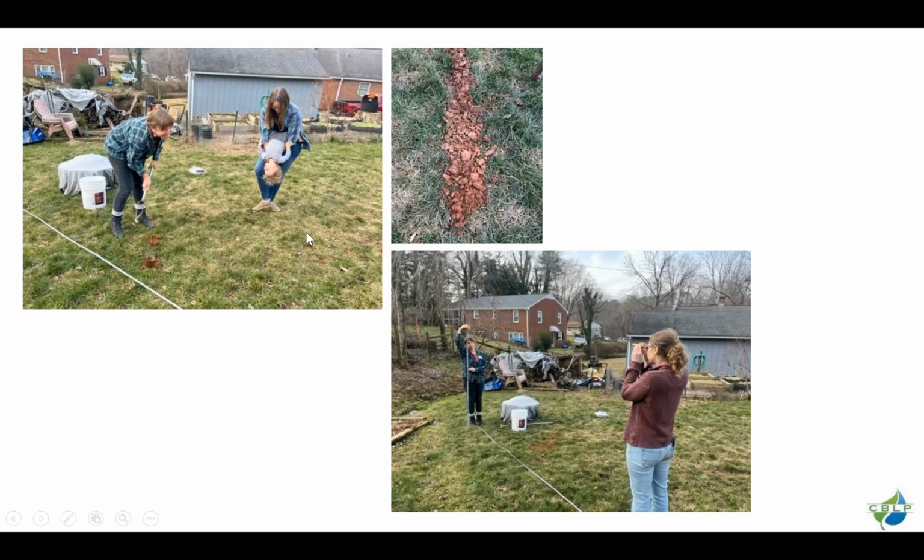The designer, whether it's the property owner or a design professional, will have to do the same thing, but you might want to get an idea of the soils. The other thing Megan and Courtney are doing here is getting the slope along where the practice would be. This is a hand level that Megan's using with a pocket rod. We'll talk about some of the site assessment tools in a little while, but just easy field tools to get things like soil and slope.